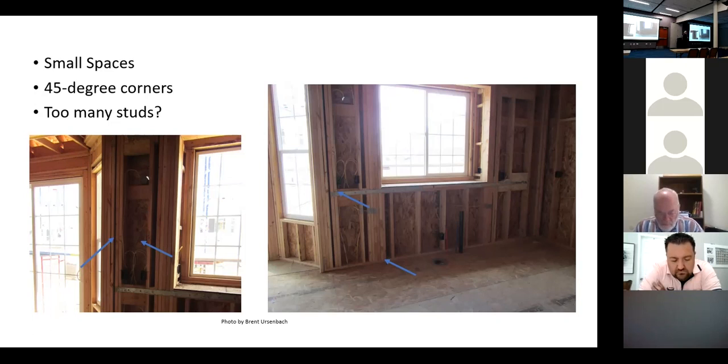What's the R-value of wood? It's about R1 per inch. So we put in an R21, or we net and blow an R24 into that cavity, but we're only at 5.5 or 6 where the stud is. And this wall right there, if you look at it, is more than 25% wood when you take into account plates and everything. Standard framing practices, 16 inches on center, end up somewhere around 20 to 25% wood, and the balance is insulation.